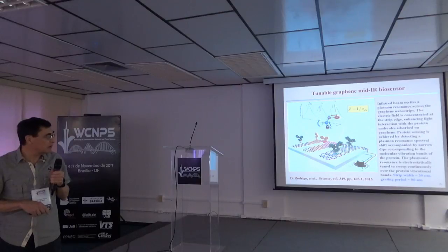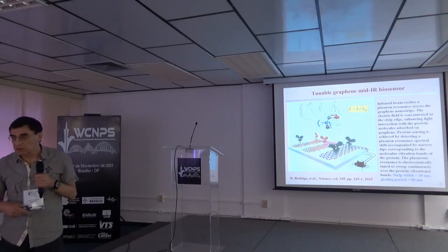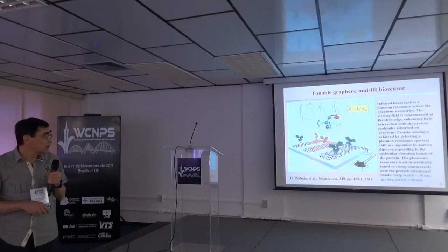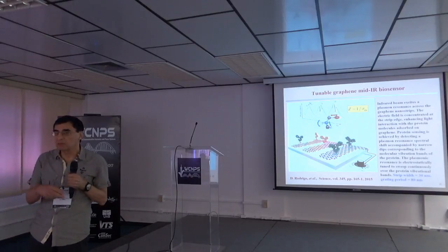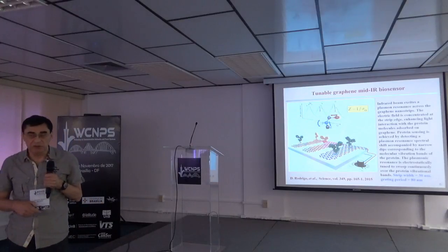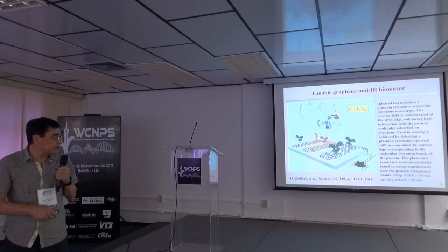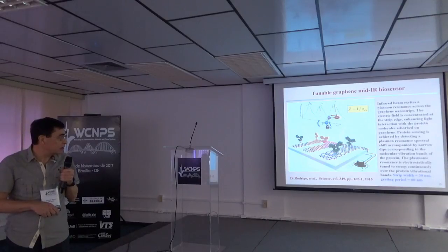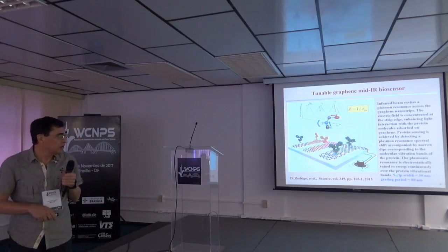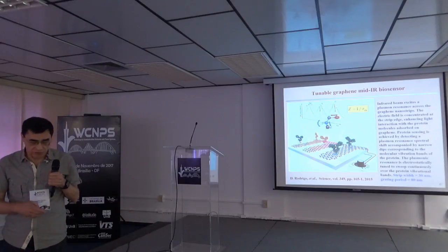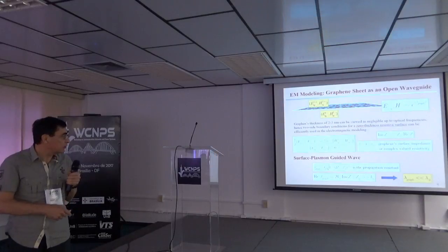And the frequency or wavelength of each resonance depends on the refractive index of the outer medium. Therefore, by measuring these resonance peaks, one can judge the concentration of some material in the analyzed medium. And this is the physical basis of the sensing. These resonances are here in the infrared range. Therefore, each strip has a width measured in nanometers. However, if you make the strip wider, in micrometers, you can shift these resonances into the terahertz range. And I will be concentrating on this topic.